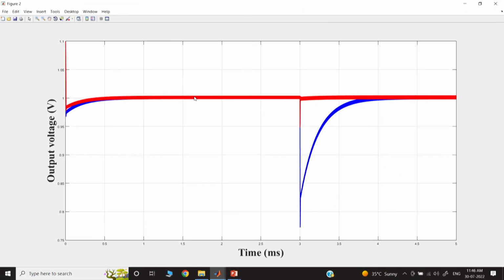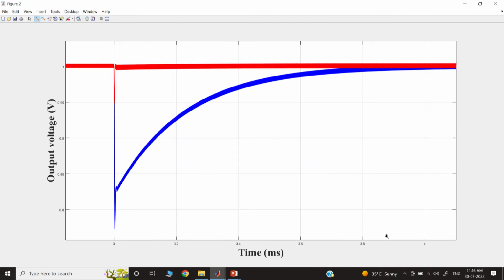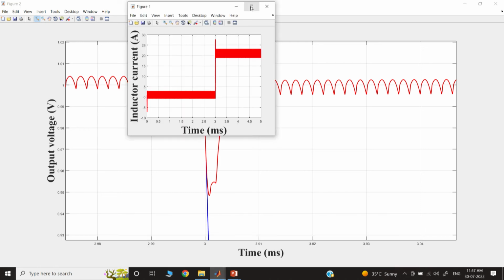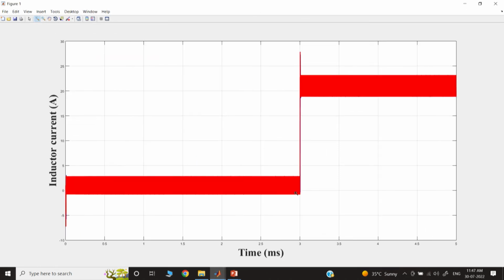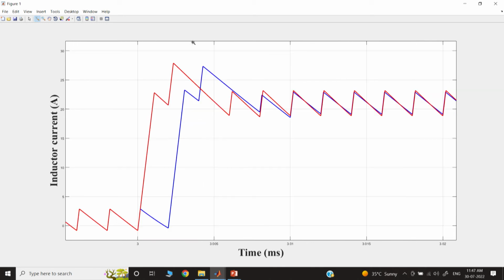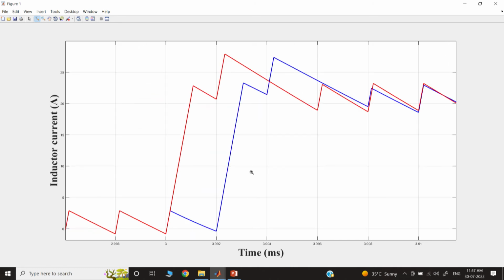So, you can see because of the load feed forward, the response is extremely fast. You can see this is extremely fast. It is almost like time optimal. That means you can see the inductor current will come back, red color. It is not exactly time optimal, but because there is no load feed forward, there was an initial delay in the voltage, and that was causing one of the issues, the additional undershoot.